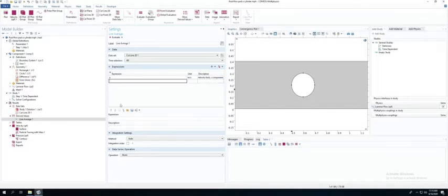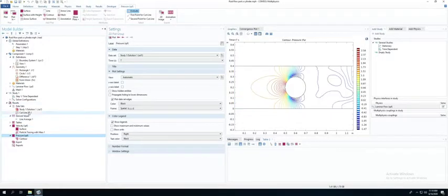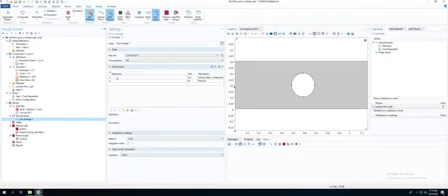And then for the heck of it, I'm just going to grab the pressure. So I enter in P as well, because I may also want to do a parametric study analysis on the pressure as well. So I'm doing the velocity, which are the two that I calculated, and the pressure. I'm going to go ahead and grab those two and calculate that. Pressure is automatically in Pascal. If you're using something else, make sure you change your units so they follow correctly.